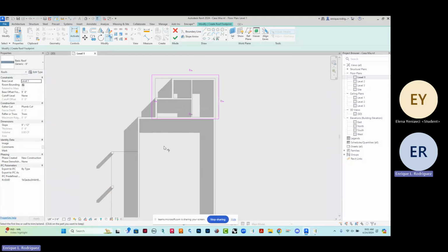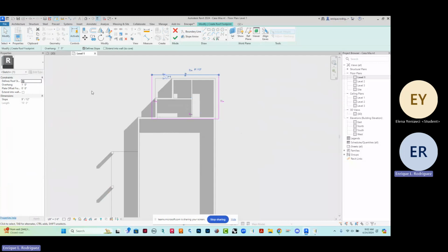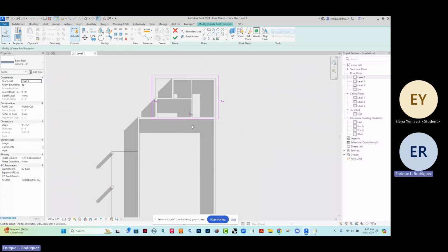And if you look at some of the handouts for the Mallory, we have a gable end condition here, and we have a gable end condition up against the second floor right in here. We do want to keep our pitch here, and we want to keep our pitch here. If you look at these little triangles, those are basically for your slope and your pitch. So the first thing I want to do is click in here, and I can remove defined slope. I can do it up here, or I can do it over here. I'm going to remove defined slope on that one, and I'm going to remove defined slope on this one.